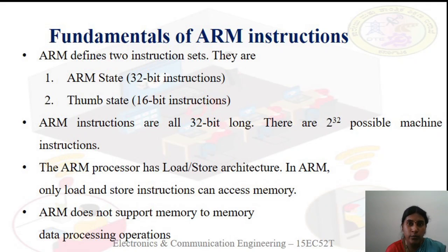Okay. Now we will see what we mean by load and store architecture. What do you mean by loading? You already saved some data in a memory. Now you want to take the data into the register. Getting the data from the memory is called a loading operation. Then what do you mean by storing? Before fetching, we have to store some data in memory, right? So putting the data into the memory is called a storing operation. So, in ARM, we can read or write the data from the memory only by using this load and store architecture.